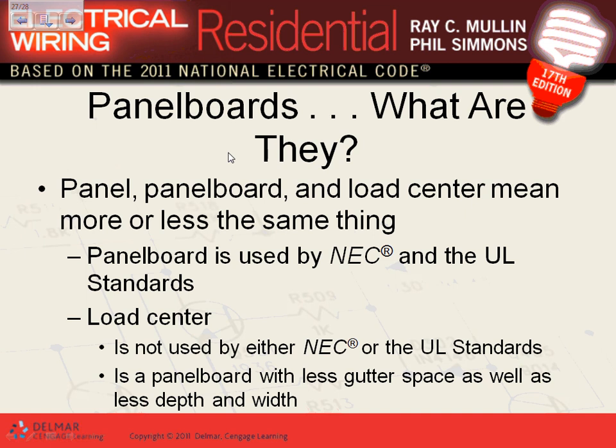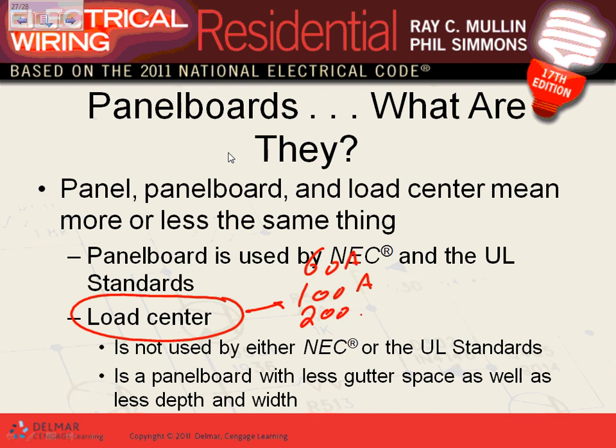I want to tell you one thing, because we're residential, we will open this can of worms as we move into commercial, because that's where they are. If you're residential, you're doing load centers. As far as the NEC code is concerned, they're all panel boards. As far as the industry is concerned, a load center is usually 60 amp, 100 amp, 200 amp, maybe 300 amp. These are called load centers.